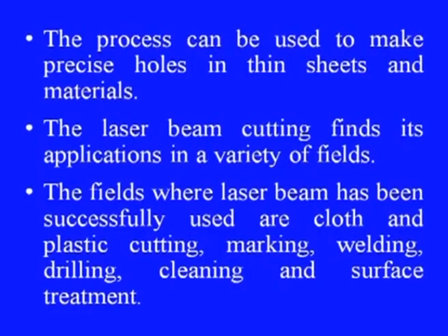In this process, the output of a high power laser beam is directed in a programmed manner towards the material required to be cut. The high amount of heat thus generated either melts or burns or vaporizes away the material at the focused zone. The process can be used to make precise holes in thin sheets and materials.